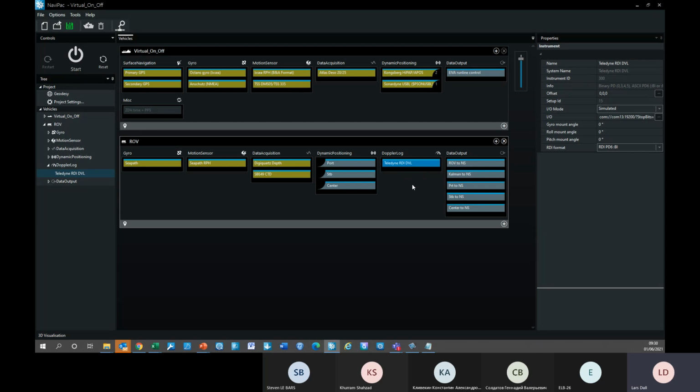The principle of a Doppler log is that it sends out bursts of sound vertically in 4 directions. The 4 transducers are tilted slightly, but they're still sending the bursts out vertically or close to vertical in 4 directions: forward, backward, left,